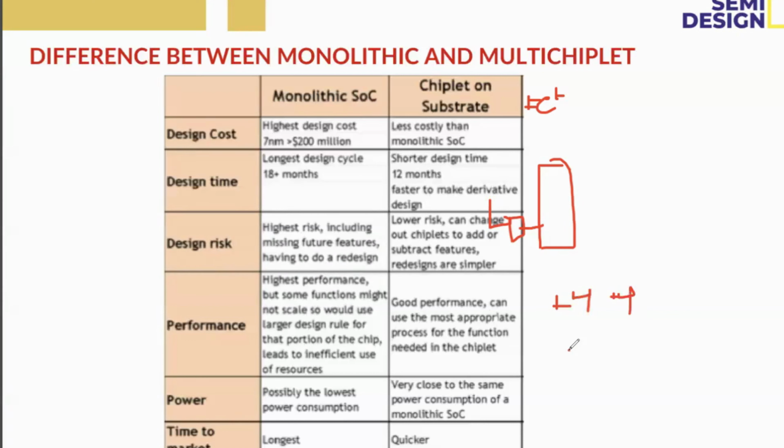Suppose it starts with address 20. Again, the next address will be 24, next 28, next 2C, like that. So this will be the address. First it will fetch the instruction from the address, and there will be some other blocks also involved. Whatever program we are writing, that instruction it will fetch from the memory, and after that it will send to the decode stage.